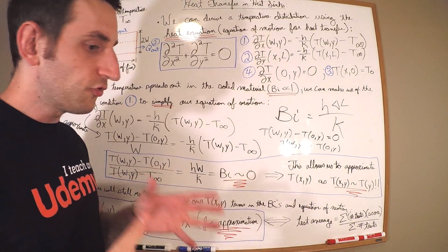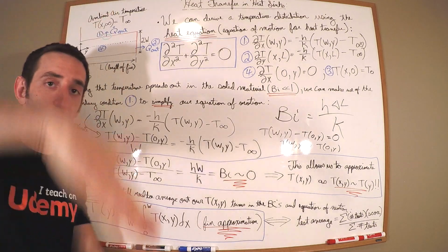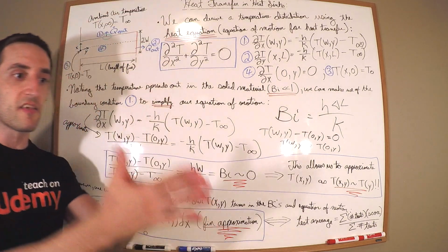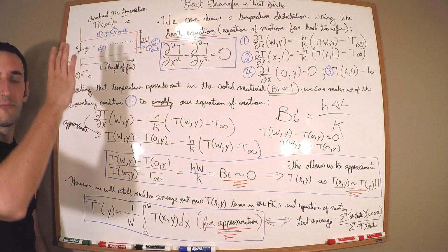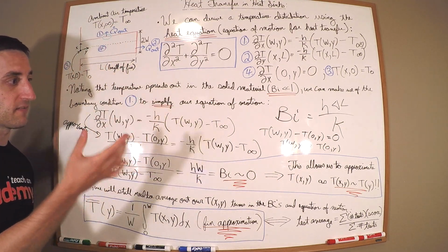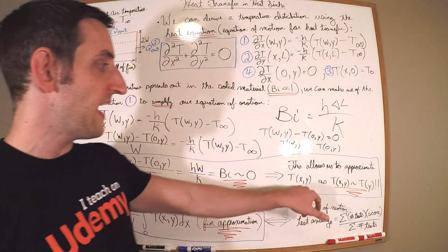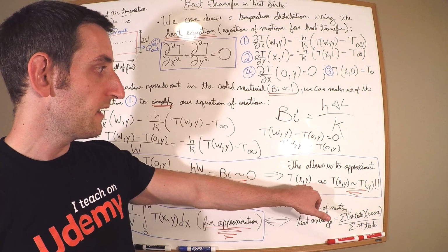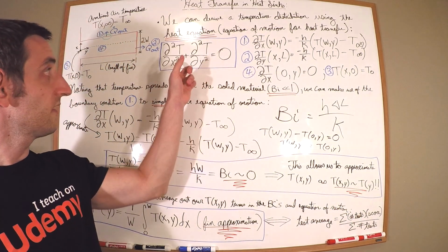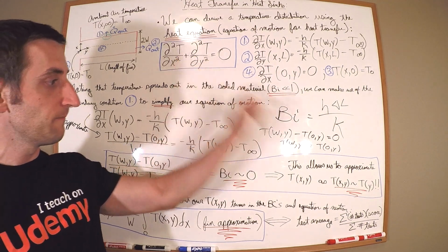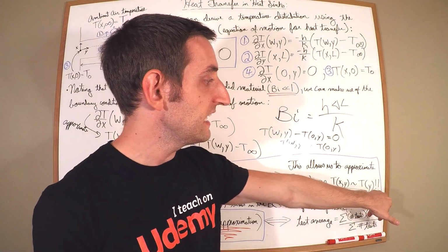And that's due to the fact that our conductivity is high and our thickness is very low. So it can spread out very quickly in that fin in the x direction, okay? So it's driven by the geometry and the material properties. And as a result of that, it means that the temperature distribution does not depend upon x. In essence, we could drop this guy out here, which is going to allow us to get rid of that guy shortly. And we can approximate Txy as approximately Ty.